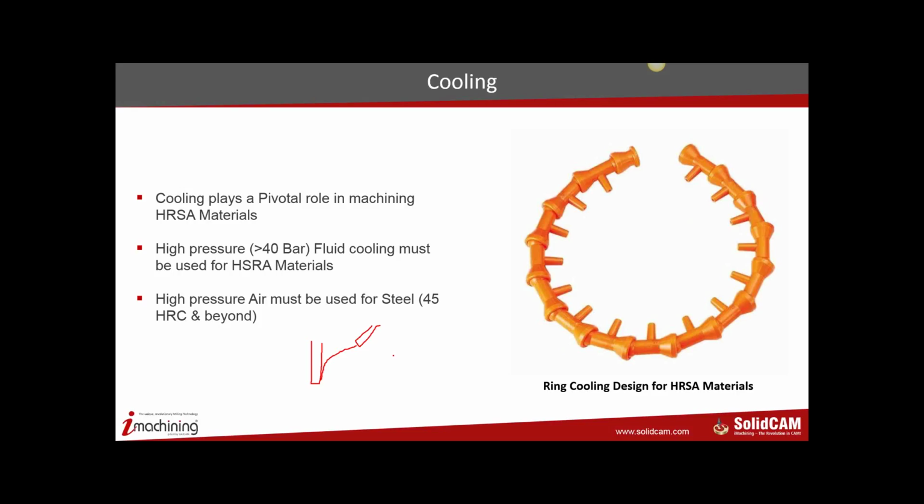And the other thing is that if you have this kind of cooling, and let's say you still give 40 bar pressure, so the coolant is hitting the tool at 40 bar. This is still not enough, because the other side of the tool is still open. It still doesn't get the coolant because it is still in contact with the material. You have got this portion of the tool still in contact with the material.